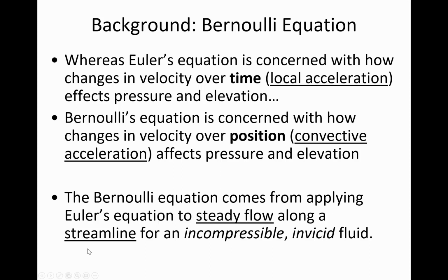Bernoulli's equation applies along a streamline, and we'll talk more about the specific details of that, but what it means essentially is that, remember, streamlines are those vectors that indicate the direction of flow. And we looked at a picture of smoke going through a wind tunnel, going over the hood of a car and up over the passenger compartment. From the smoke, we could get an idea of what direction the wind was going, and relatively speaking, where the velocity was increasing. So when you apply Bernoulli's equation, you have to be on the same streamline upstream and downstream. Now these last 2 are especially important.